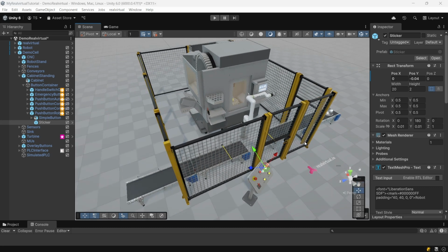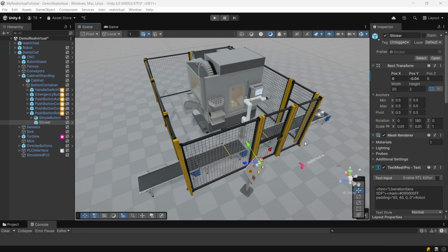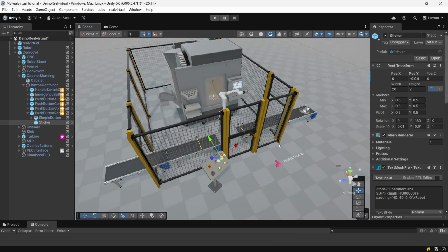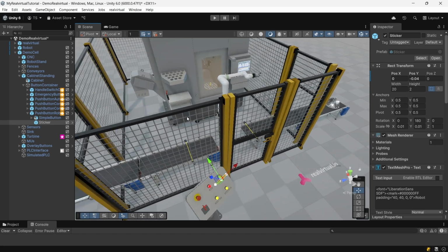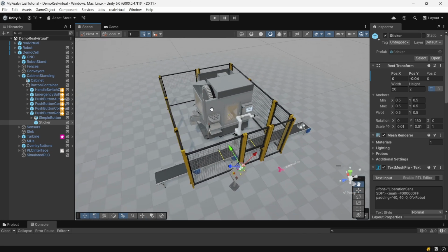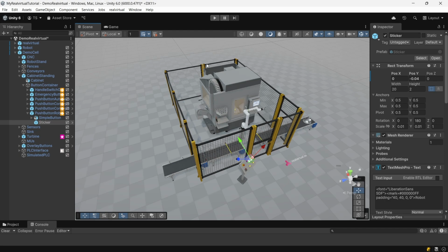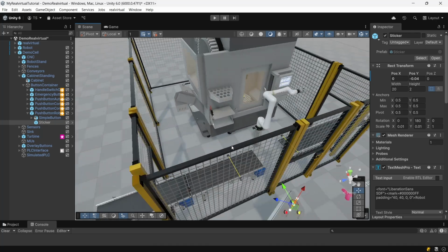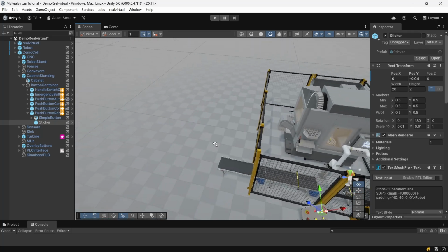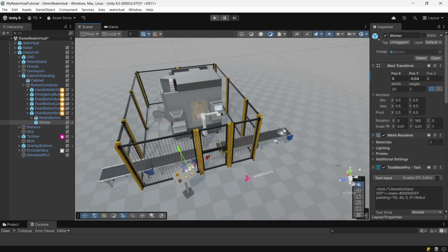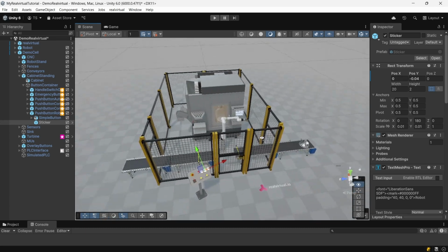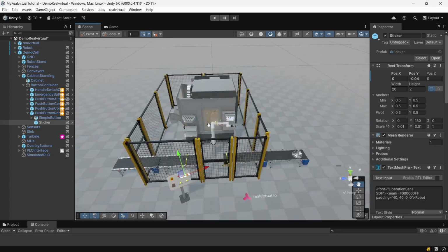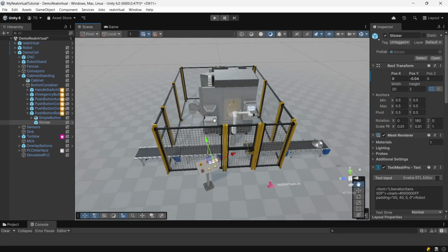Now we are fine and everything we need for using realvirtual is inside our project. Now let me first give you some basic hints and tips on how to use Unity. First of all, mouse navigation in scene view, while you're not playing as well as in game mode: with the middle mouse button you can zoom in and out. With the right mouse button you can rotate, and for panning you press the middle mouse button and you can pan.